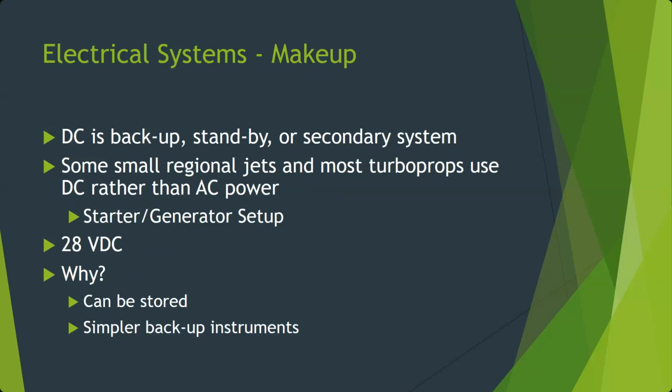The other half of the electrical systems, DC, is typically used for backup, standby, or secondary, with the exception of some avionics that do require DC. Okay? And DC can be its own system, or in some cases, things plug into the AC system, and then they have their own transformer rectifier in them to create DC for their use. That's what the charger is on your laptop. That's what the charger is for your cell phone. That little power block that plugs in,